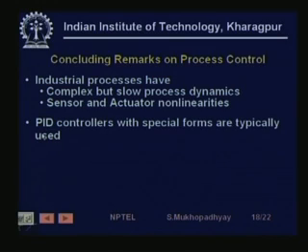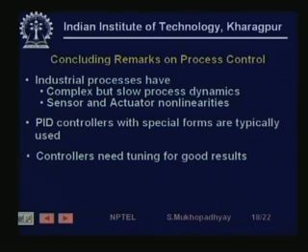And typically in around 90% of the cases PID controllers are used, sometimes with various special configurations for anti windup, for bumpless transfer, and special structures for feeding back derivatives, as we have seen. Generally the controllers are PID, they are extremely common, and PID controllers have to be tuned.